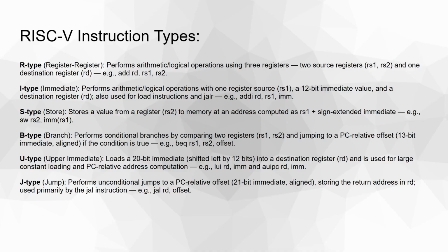Those can be helpful for initializing your programs or initializing values, because your zero register, and this is important, your zero register will always be zero. Even if you try to write to it, it should always remain zero. There are multiple ways to keep it at zero. You can either have the write enable always be low.